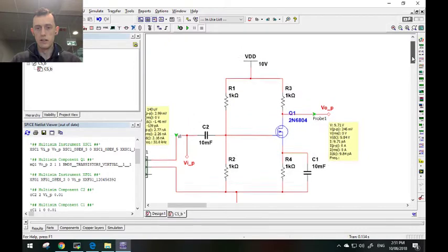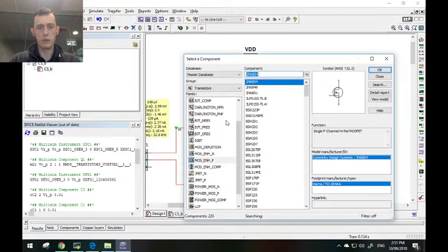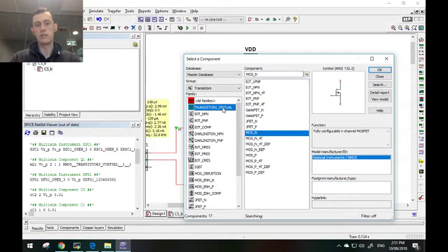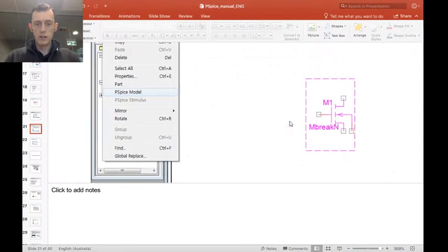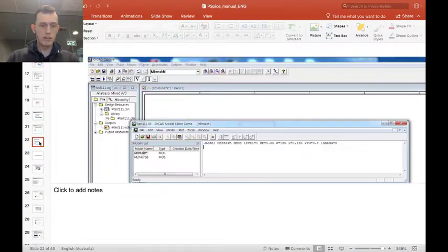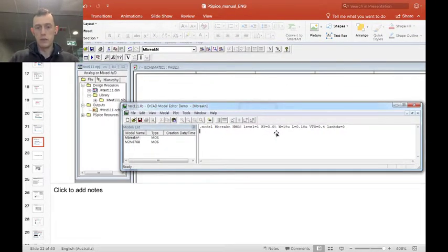Zoom in a bit. So we can see here's the P channel. We need to get rid of that one. And what we'll do is place a component. This time around though, we'll actually make a change. We'll use a virtual transistor. This is a level 1 design. There's a couple different levels of design parameters you can use for a MOSFET within the simulation. Now, you can find that we are actually going to be using a different transfer function. So we'll enter this information in.